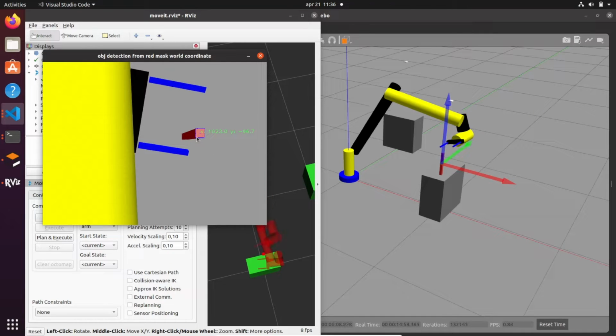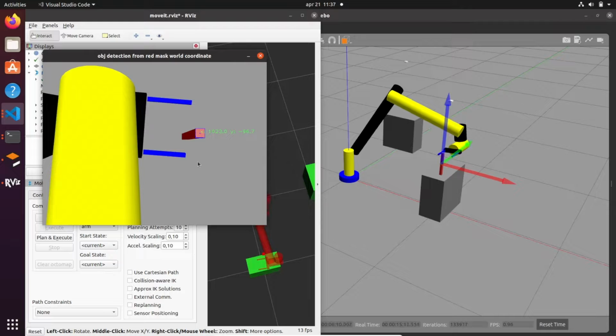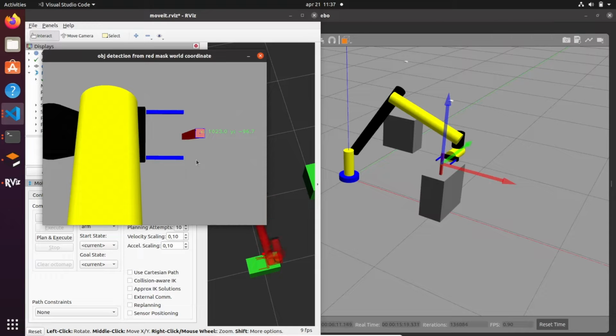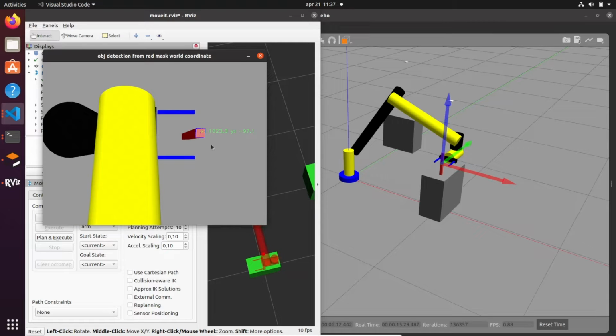Finally, today we will deploy a very common manufacturing industrial application as a pick and place using a 2D camera to sense the environment. In particular, we are going to use OpenCV to detect and track where the object to pick is. And we will use inverse kinematic algorithm to allow the end effector of a 6-axis robot to reach the target position and place the object where we want.